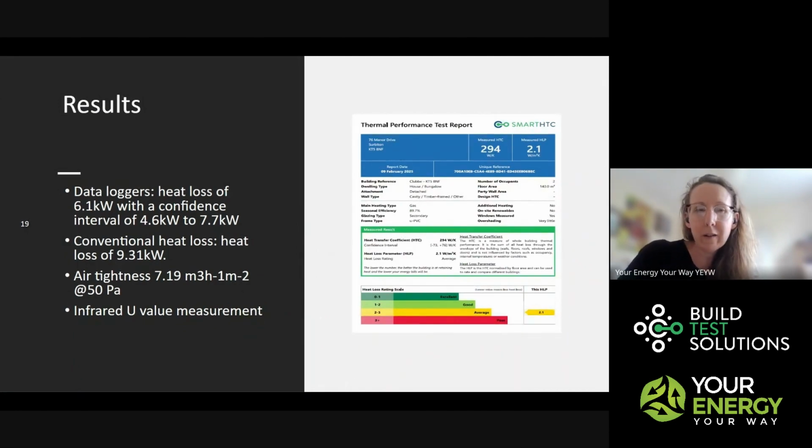So you can explain the science, but in layman's terms, you point something at the wall for an hour or so, and you work out at that point what the U value of that particular wall is in that area. And interestingly, these were solid walls, and the U value came out between the two places that Richard measured at 1.